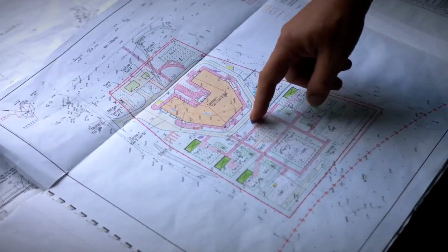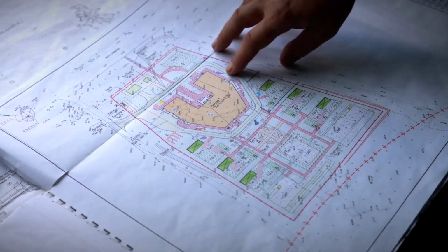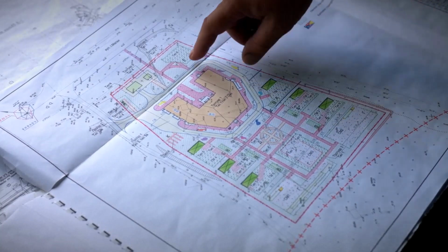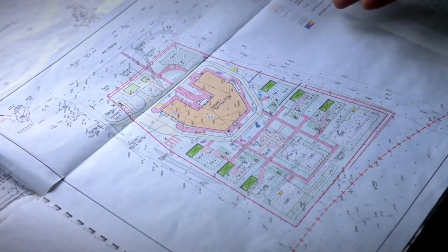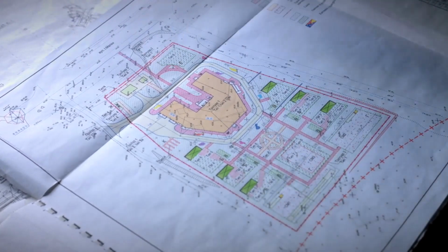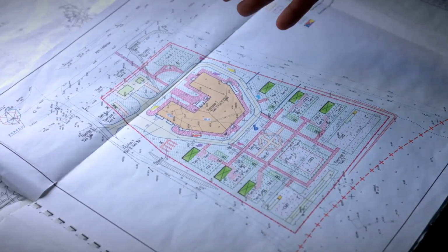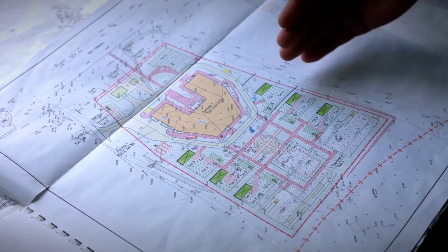Thoroughly review the drawings and schedules, noting each item to be constructed with concrete. There may be 5 foundations that are the same size. Count each one separately and document the dimensions in a spreadsheet. List similar items together in the spreadsheet. Use of a process like this will reduce the likelihood of concrete structures being overlooked.